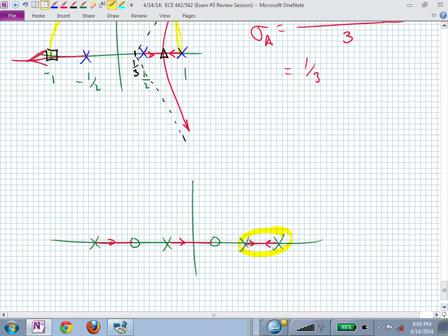Depending on all these values, let's say that your centroid ends up being there. Then these are going to do this. And the relative maximum will determine where they break away. You may have no hope of stabilizing that system without some additional poles and zeros or a more elaborate controller. It depends on where all of those are located.